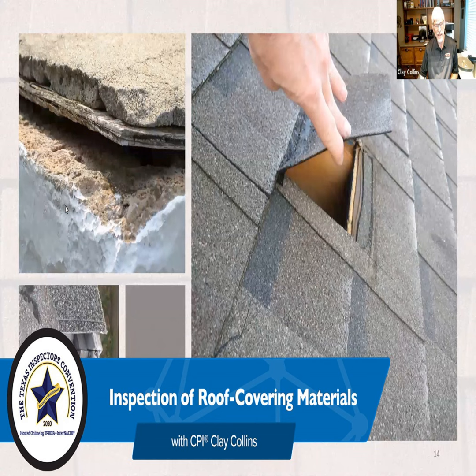Asphalt shingles. The biggest thing that I learned is damage to those shingles can occur during high temperature. And unfortunately, that's something I had to learn by experience. It was very hot. I stepped on the roof. I thought the slope wasn't too bad. I thought I could do it safely. And when I got down, I saw that my activity had worn some of the aggregate off.